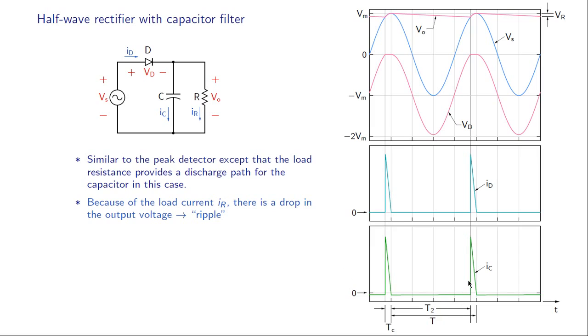This figure shows the capacitor current, and in this interval the diode is not conducting, and therefore IC and IR are the same, of course with the negative sign. So IC then is minus IR, and you can see that this is over 0 here, and the IC value, which is the same as IR in magnitude, is very small as compared to the diode current here. These are drawn, of course, on the same scale, although the scale is not shown.